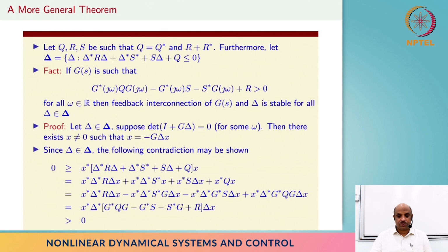Second thing is basically there's no way that we can guarantee that we are not missing some specific key points where that condition could be violated, right? I mean, some continuity conditions and things like that may help, but not beyond that, right? Whenever we use Nyquist plots or Bode plots and things like that, it's semi-analytical. We have the picture in front, but we actually have an analytical way of convincing ourselves that that picture makes sense, right? But when it comes to MIMO systems that we are dealing with here, if it is simply some matrix condition that is in frequency domain, then checking that is going to be very difficult.